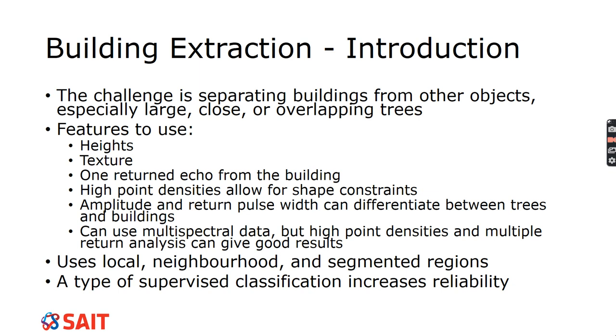We can also do classification. So if we do a supervised classification with our LiDAR, which you can do, you don't necessarily just need to do it with regular remote sensing data. You can apply a supervised classification, and that increases the reliability. So you go out, you can collect field data, and you can say, these types of points are going to be this type of land feature. These types of points are going to show these, and you can create a supervised classification with LiDAR. So that really increases the reliability of your final result in finding those building extractions.